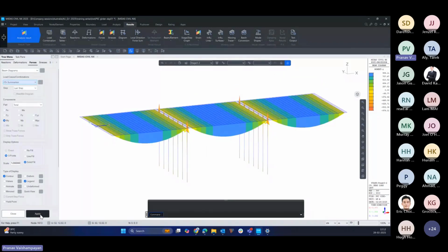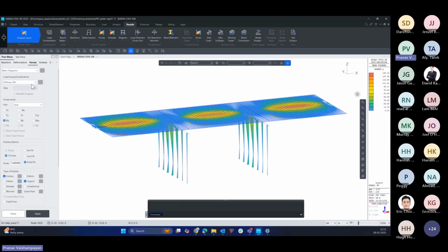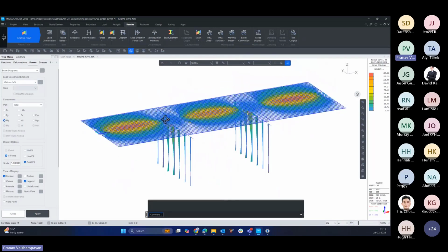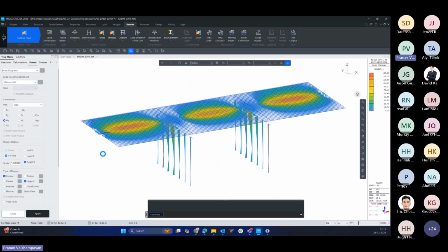I'll check on summation. Similarly, we can also check the creep primary, tendon primary, or shrinkage primary options and secondary values as well. Let's check one of the other values in post CS, which is the maximum moment for moving load. We'll select this. MV max represents our envelope of loads for each element.